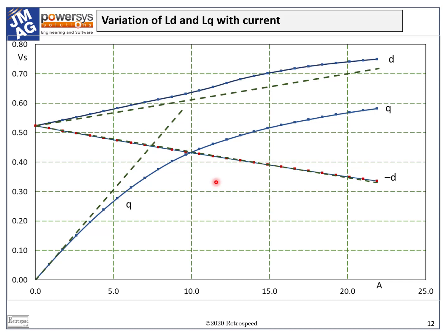Once we know the flux linkages and the current in the dq axes, we can immediately calculate the torque and the terminal voltage. An estimate of the torque is obviously needed in the field-oriented control scheme. If we have a PWM current-regulated inverter, we will be controlling the current.